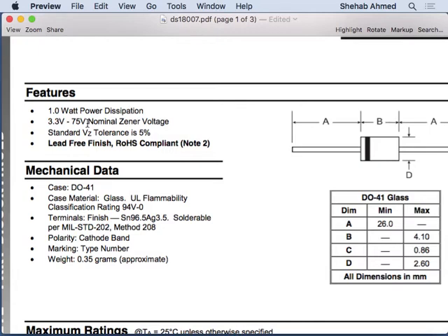We said at the Zener voltage, the electric field that you've created in the reverse direction, remember, when you put reverse bias, the device, you are doing what? You are aiding drift, right? You are opposing diffusion, right? You are aiding drift. But if you aid drift considerably, that's the effect of this Zener diode. That's this V-Zener effect.